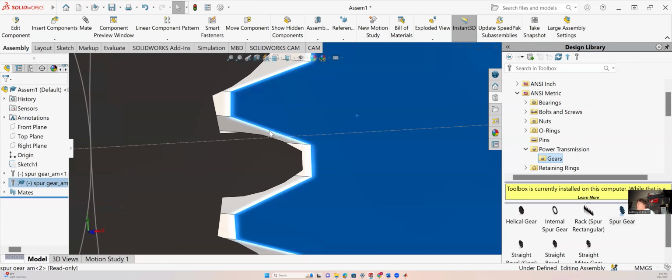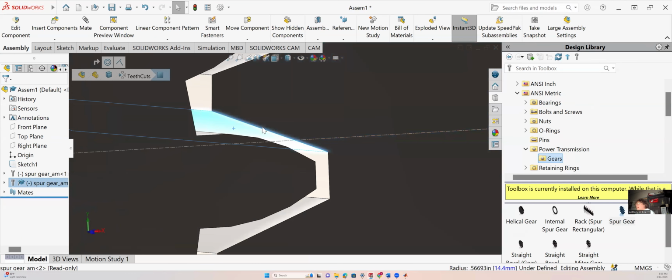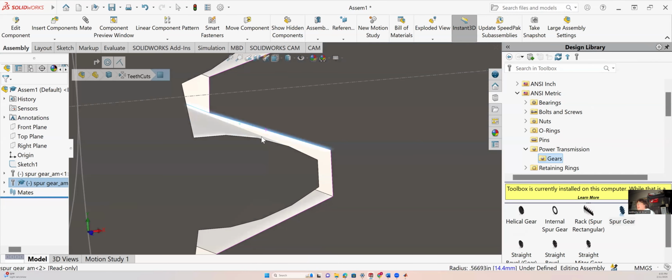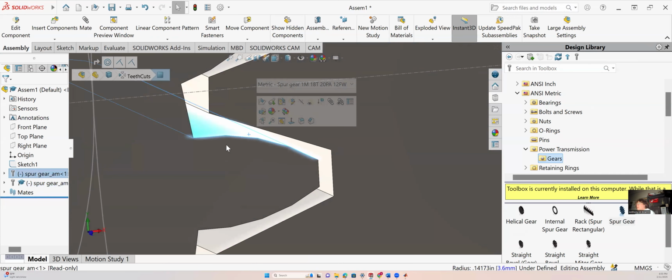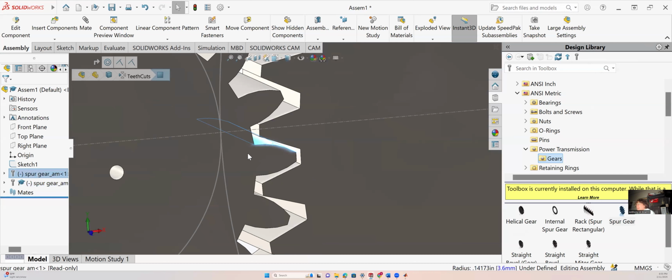And you could also see what I was talking about before. This curve here looks much more like a straight line than this curve here. Okay. And that's because, yeah, as the gear gets larger, that gets flatter and flatter. And on a rack, that is an absolutely straight line. Okay. And it has to do with how these two surfaces interface. And basically the line of action that goes through like that, basically is tangent to both faces, has to stay at a consistent angle. Okay. And that has to do with your pressure angle.